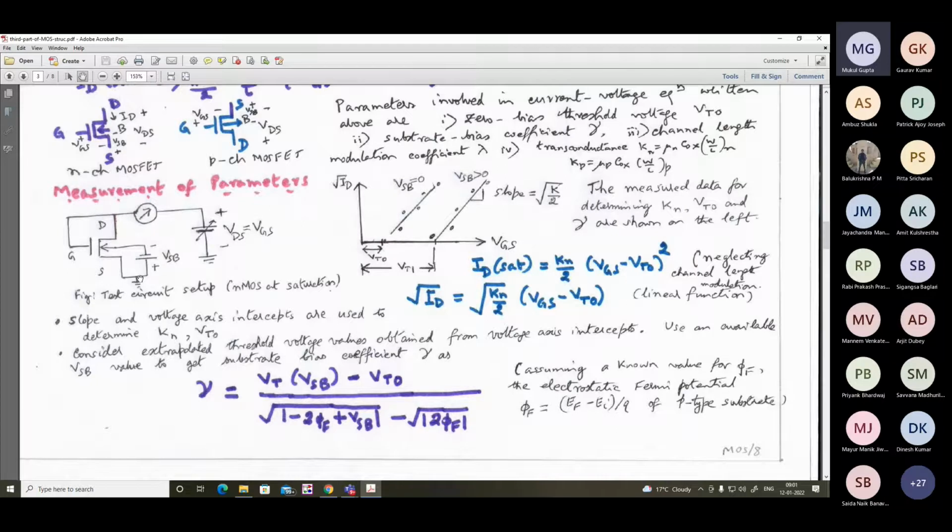Only for the bottommost transistor in a stack of transistors, the source will be the same as the body. Suppose you have a stack of transistors, like cascode structures, which you have studied in analog, or even a NAND gate. With a series placement of NMOS transistors, only for the bottommost transistor is the source connected to the body.